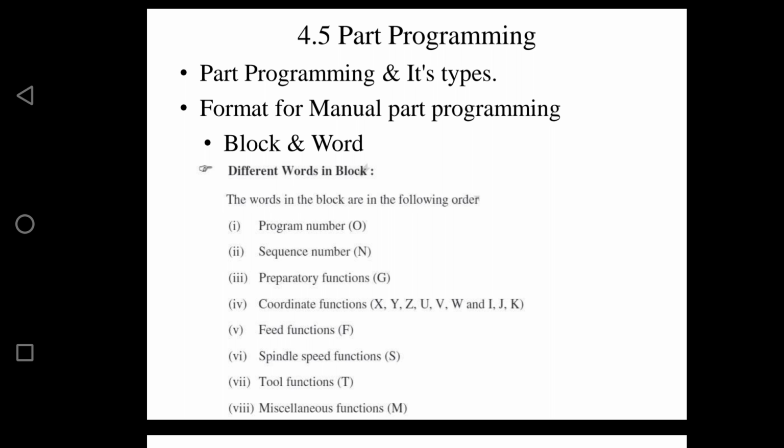Let's say I have an example. You write T08 in the program. What it indicates is that we have tool number 8 in tool turret position 8. That is about the tool function. Finally, the miscellaneous functions, which are represented by the letter M.